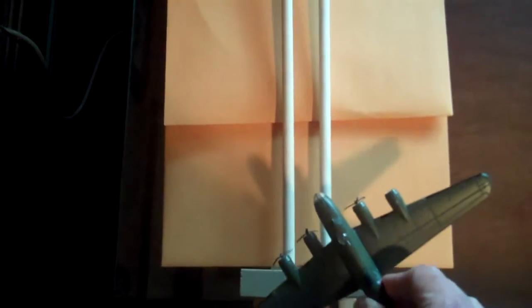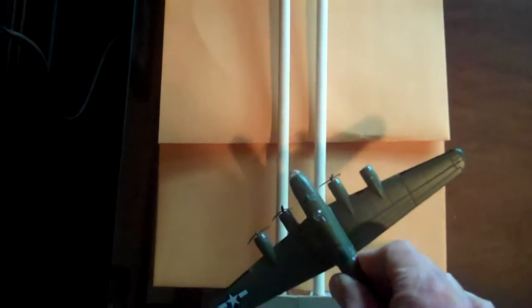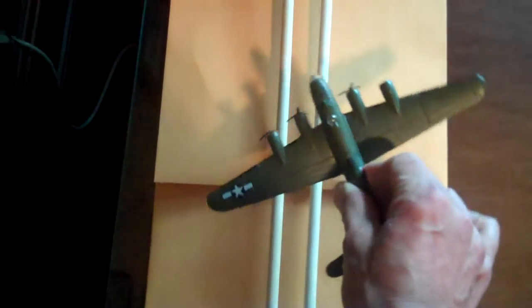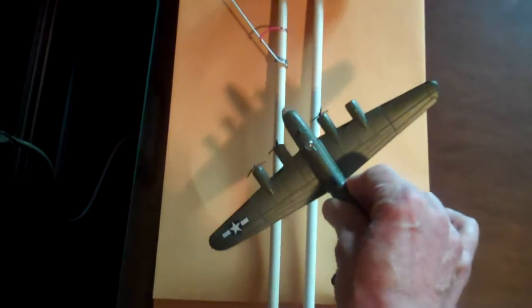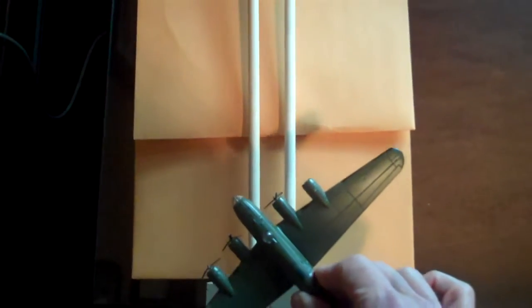The Norden Bombsight has a turn knob which will allow the airplane to be turned into the wind, but it will be repeatedly blown off course unless a drift angle is established, and this is done by using the turn knob and the drift knob together. This is called killing the drift.